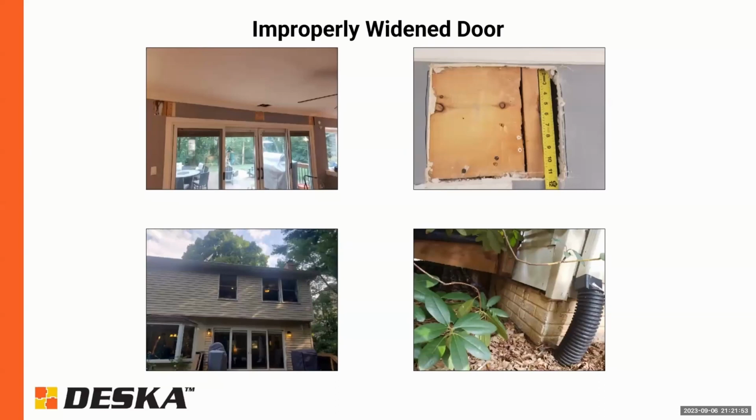It was a 12-foot opening, and if you look on the outside here, it's supporting a floor above, which is also cantilevered, as well as a roof above as well. And the existing beam was only rated for about 30% or so of the actual design load for the home, or I should say the working load for the home.